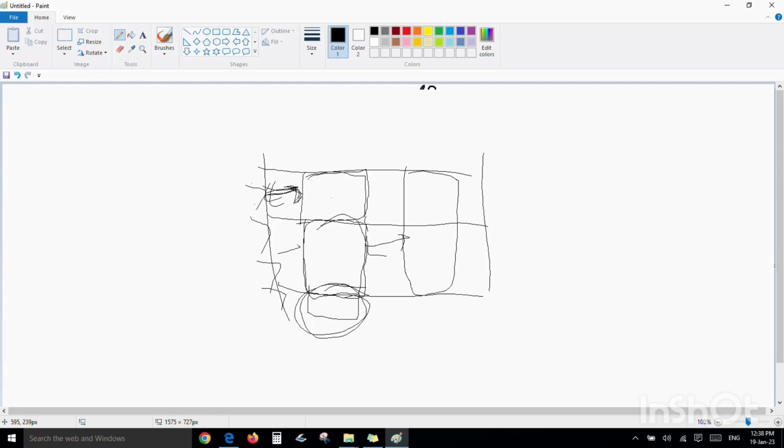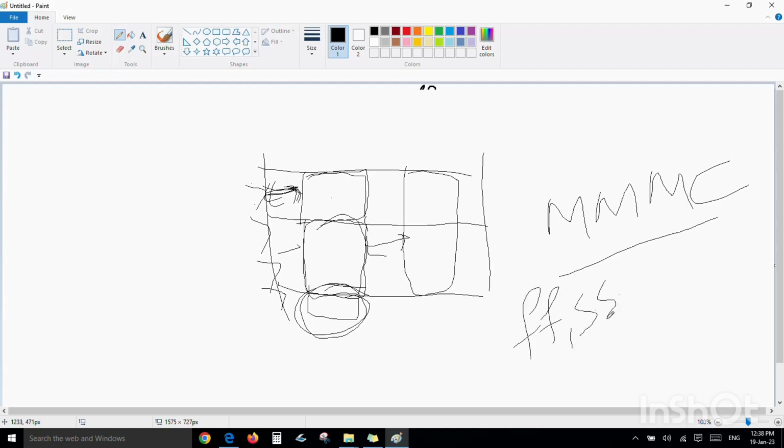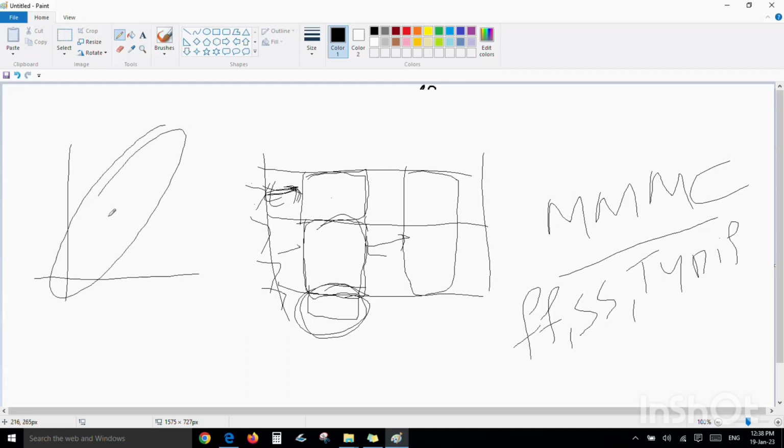And we used to create MMC files. MMC files are nothing but multi-mode, multi-corner files. So why do we create MMC? Multi-mode, multi-corner. I need to close my chip at all the corners: FF corner, SS corner, typical corner, and there are so many other corners. If you had the graph of that, it will be like this. So this is going to be some FF corner or SS corner here.